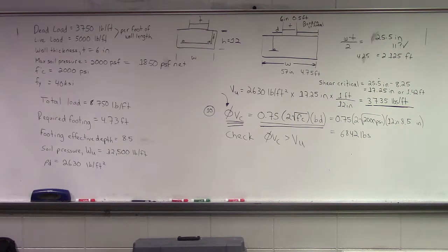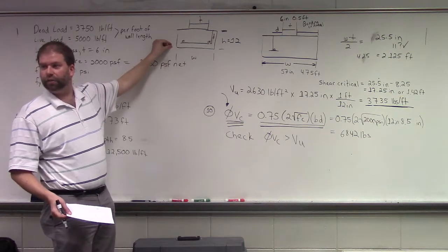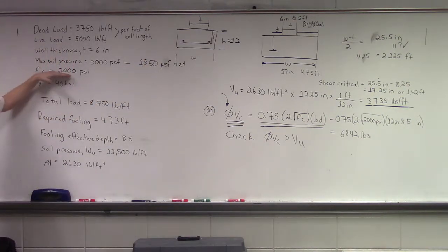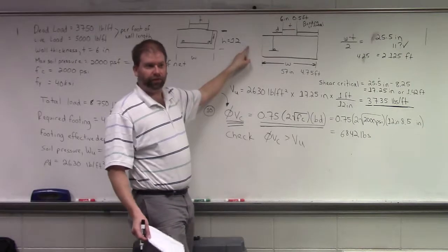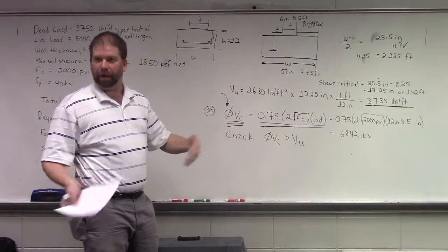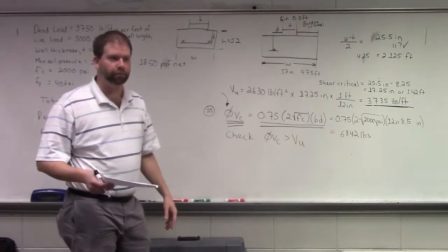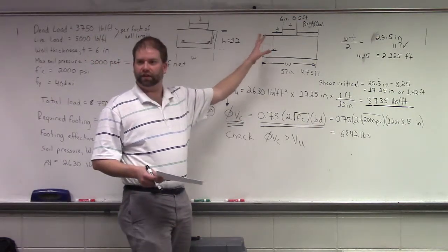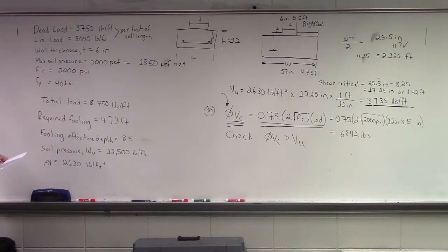If we're talking about shrinking our footing, when we think about total cost, how much is it going to cost to get fairly low grade concrete pumped into a hole on a construction site versus figuring out and sharpening our pencils on the amount of steel and installing steel on site? I'd rather pay for the concrete and pump the concrete into the hole, right? Does that make sense to everybody from an economic standpoint? Rather than mess around with placing steel and sharpening our pencil on that one. So you get a safety factor.